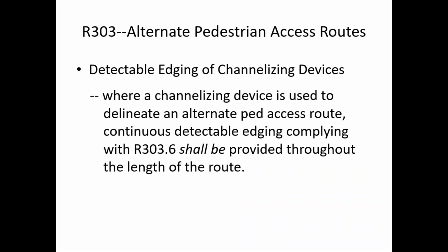Edging, detectable edging of channelizing devices. And PROWAG says where a channelizing device is used to delineate an alternate pedestrian access route, continuous detectable edging complying with R303.6 shall be provided throughout the length of the route. So notice PROWAG requires the continuous detectable edging.